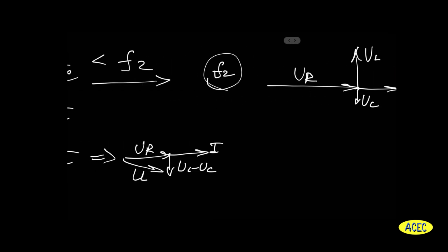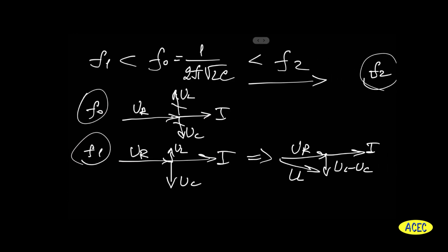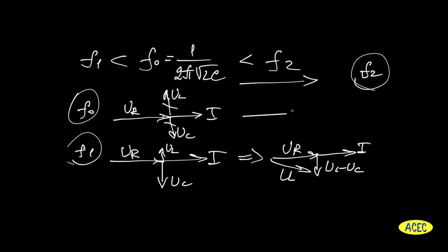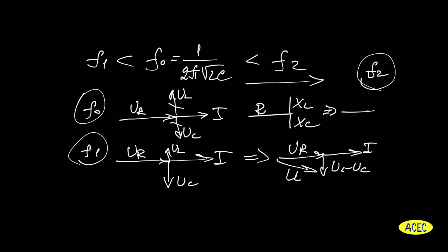The same we can see on impedance triangles. In the first case, we will have that reactive resistance, or total reactance, is equal to 0. Means active resistance is equal to circuit impedance. And in other two cases, we will have the following impedance triangles.